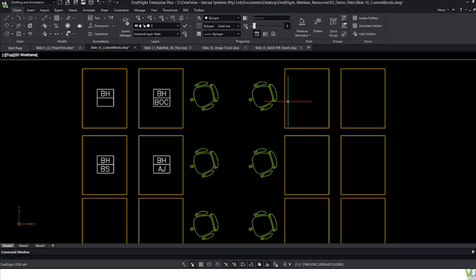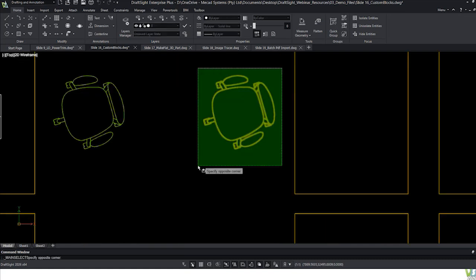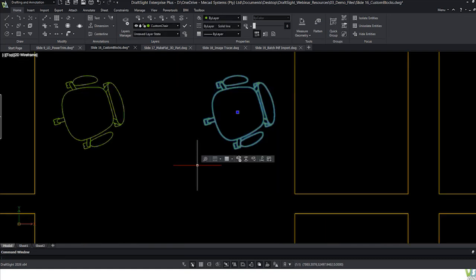A normal user would highlight, then look for the modifying tools, look where rotate is, or even type rotate and try to rotate this as well. Then you can even mirror this feature if you want. But the nice thing with blocks is you can actually customize inside the block and give it better configurations. And that's exactly what I'm going to do now.